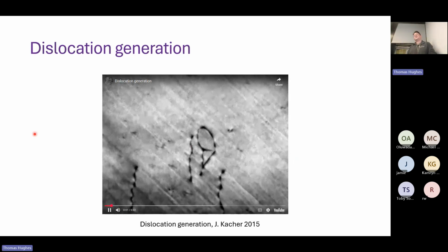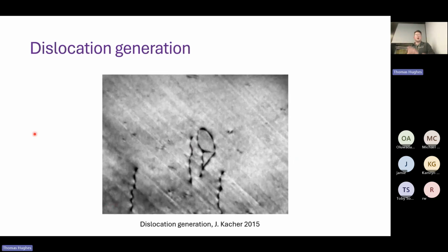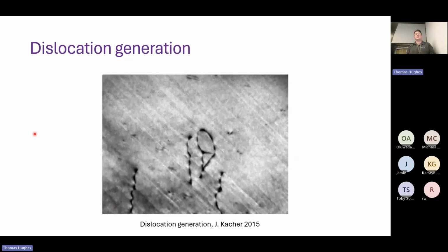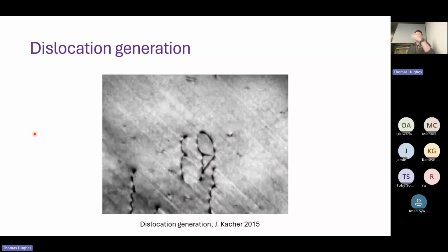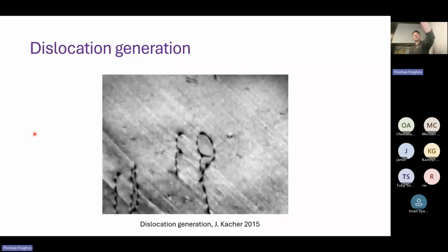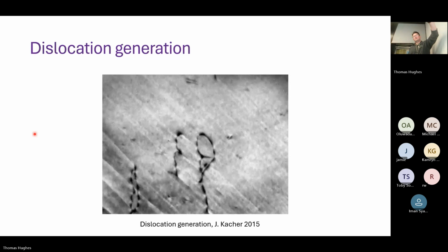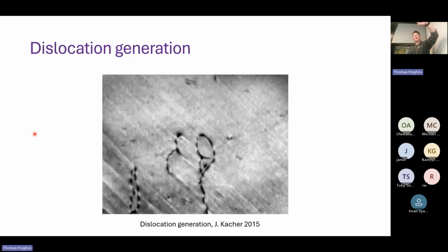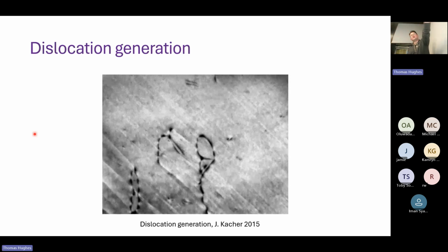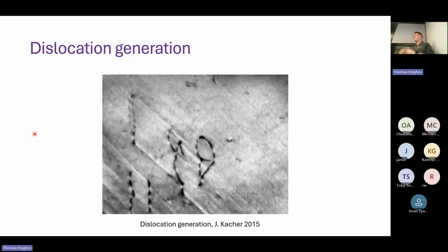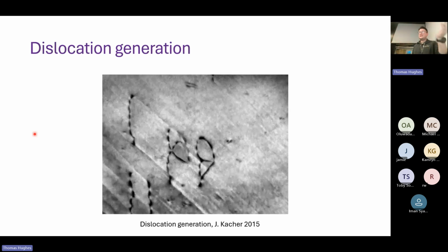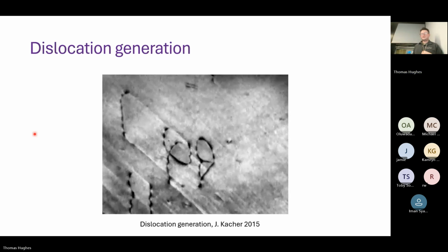Right. So we can see again, these black lines are our dislocations, our half planes that are not completely in line with our perfect lattice structure. See them moving through. And then I think this one at the bottom, as it goes in, should move now. But you can see this loop has formed, and this loop is where more dislocations will catch and it'll generate sort of more dislocations, which will lead to more material deformation.